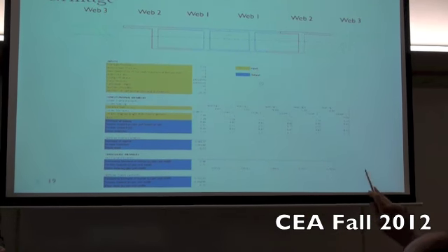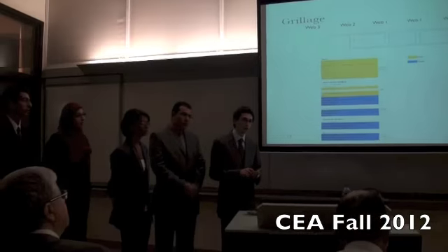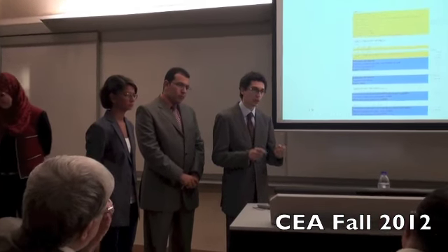You are taking it as an I-shaped section, and then you are also taking the transverse frame, so you are duplicating the material. That's why we mentioned that our weight modifier, which is how much the weight will be accounted for in the transverse member, is equal to 0, as if it's weightless. So we use the stiffness in both directions, however we use the weight in one direction.